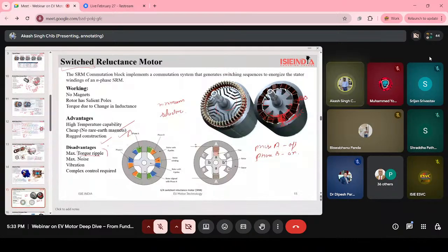Yes, the variation comes in the rotor. If the rotor is not rotating smoothly, maybe there was a fault in the Hall sensor. It is not working, it is not giving signals to the controller part. So that creates the torque ripple.